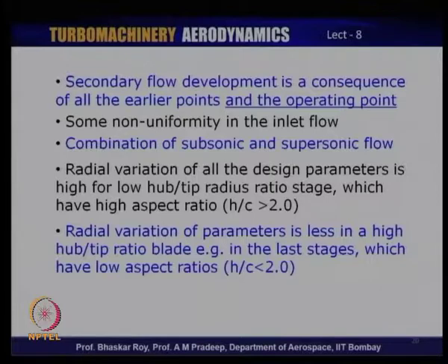Then again, it depends on the non uniformity of the inlet flow. As we have seen, the flow becomes progressively more and more non uniform as it goes through the stages. Then you have a combination of subsonic and supersonic flow. Somewhere along the blade's length you have shocks, somewhere you do not have shocks. So, that produces 3 dimensionality all over again. And then the radial variation of all these design parameters is